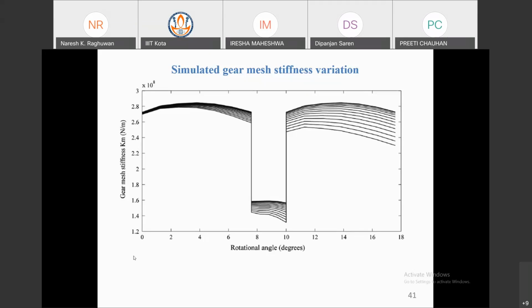With this time-varying mass stiffness, you put it in the differential equation, and you will get the simulated signal accordingly. And you will see what type of signal changes if a crack is there. So without an experiment, you will already know that if a crack is there, this type of signal will change, and if a tooth is missing, this type of signal will change. In the simulation, without any big cost for doing the experiment, you will get the signals, predict, and publish.